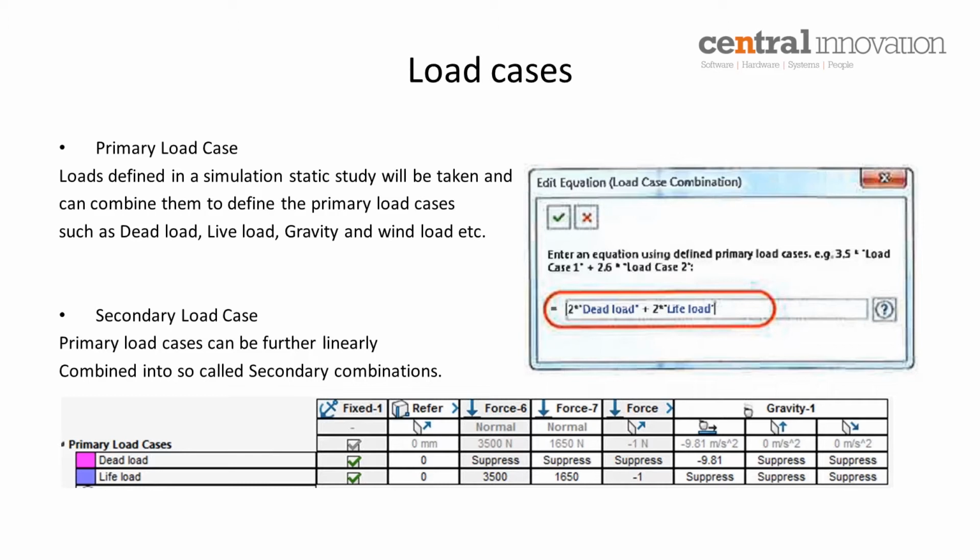For this combination, what is my structural response? How is the response of the design changing? How is it affecting my stress value? How is it affecting the deformation value? That's what I want to find out. So these kinds of combinations and equations, you can combine the load cases by using this load case manager. And also by using the primary load condition, you can define different load cases and test your design for multiple loading scenarios.